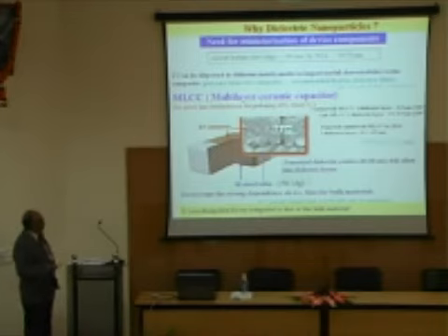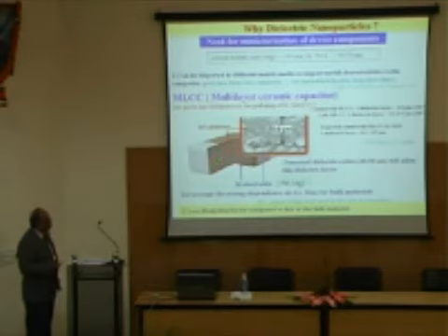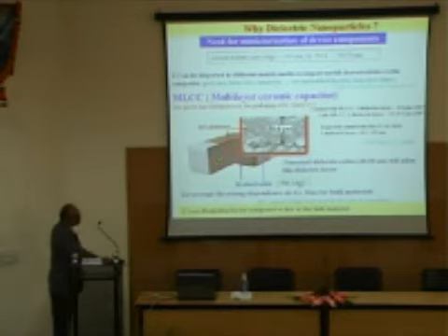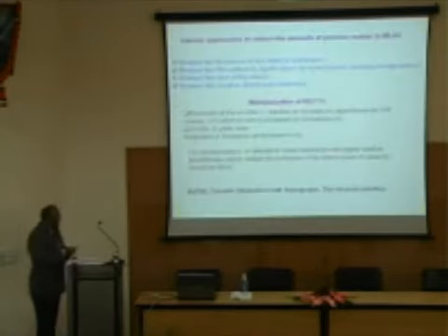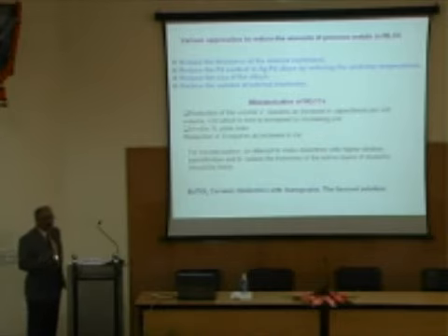So if you want to make thinner layers, you have to work with small particles. So nanoparticles of dielectric materials are very important. For miniaturization of MLCCs, you have to reduce the volume, and there are a lot of things you can do, but the cheapest thing that you can do is to reduce the size of the particles of the dielectric. But there are other things you can also do to miniaturize these MLCCs.